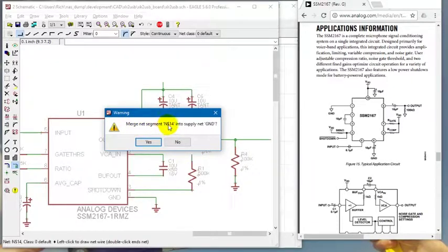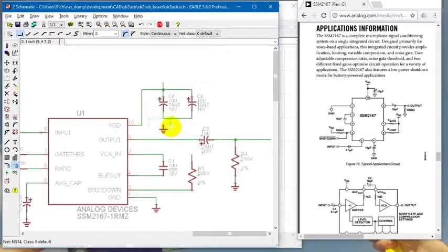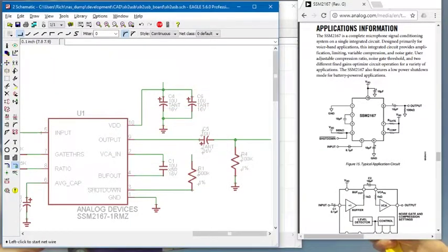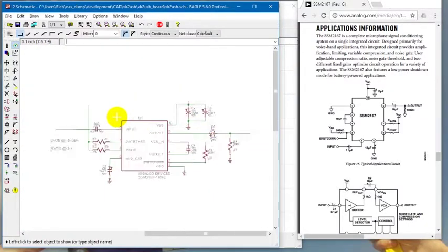So it's going to say, are you sure you want to connect $14 into ground? Because I have to call it ground. If you say no, it takes away your connection. If you say yes, then it becomes ground. And if you've been watching carefully, all of the grounds got highlighted when I clicked it with the yellow eyeball command. So that was the power of the supply line.